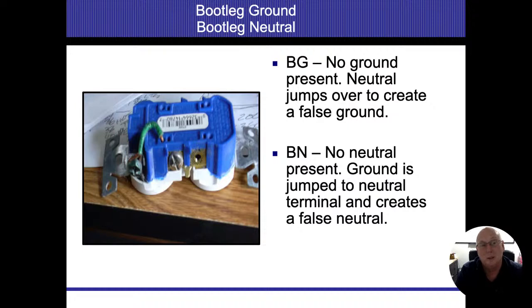Now, will this work if I have a wire come loose and an energized case? Yeah, it will. That will go ahead and get the wire over to the neutral. But in all reality, because the neutral always carries amperage, we said amperage doesn't disappear, doing something like this is basically the same thing as bonding a sub-panel. We're putting that particular ground and that particular neutral together. And if I have another ground path coming in there, I'm actually inviting amperage onto my grounding system. And that we just don't want to do.